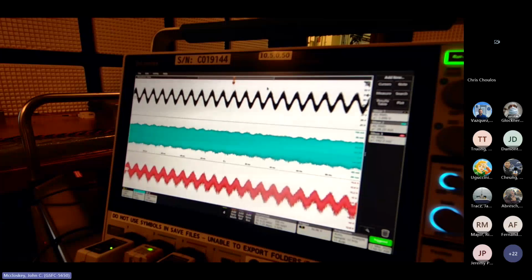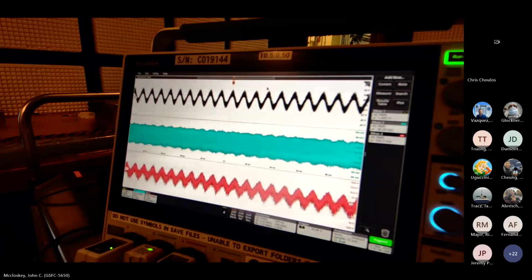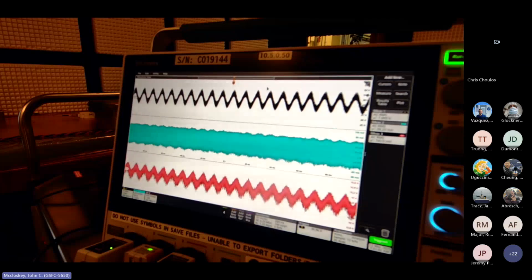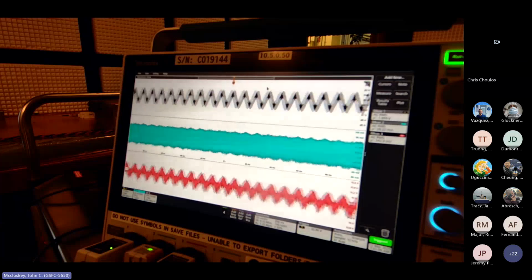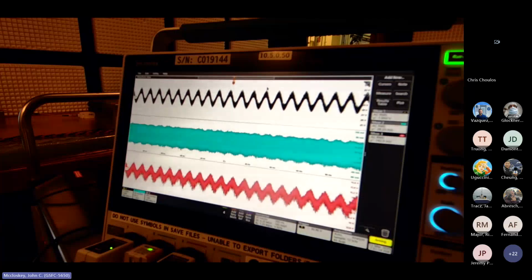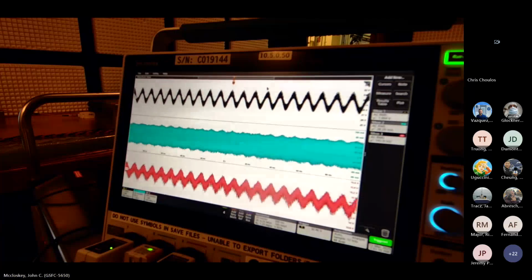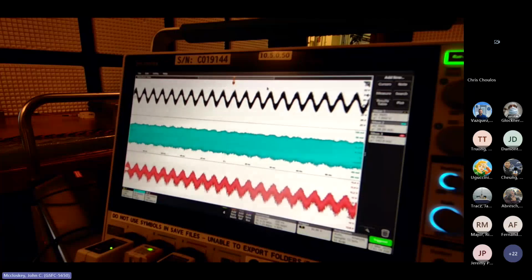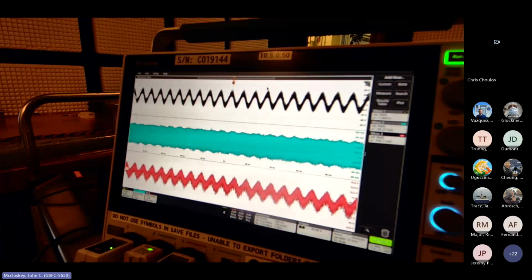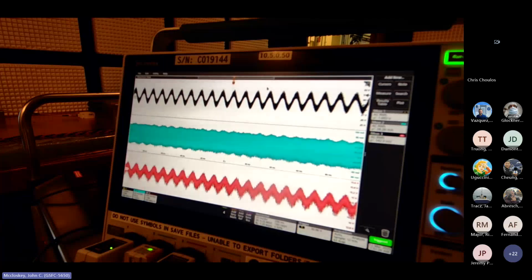So at 100 hertz, our signal generator setting is minus 25.4 dBm, and we're getting right around 1 volt, 1.005 volts. Our injected current is still about 28, which is pretty much in the noise. And our output voltage is about 142 millivolts. So it's a little more attenuated, so that's good. Well, it just is what it is, right?